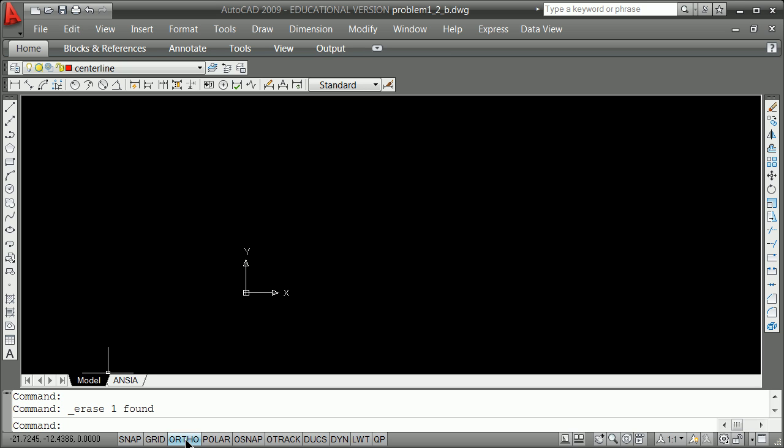and again this time show you that we can use tools like this, like ortho, or particularly polar, which is a little bit more interesting, to do things like this. Draft a box, right, or draft lines. So I'm going to draft lines. Once again, it's a great idea to go 0, 0, 0.